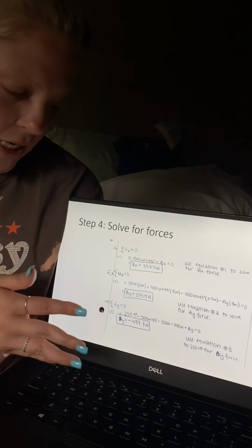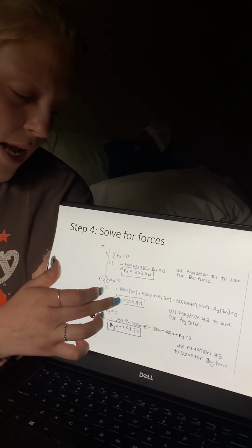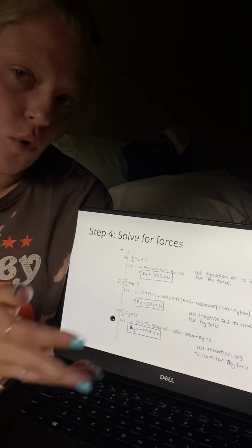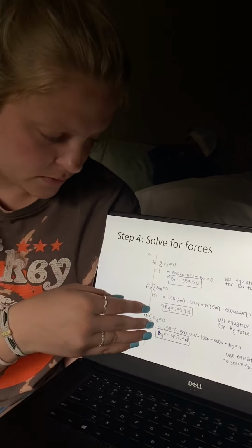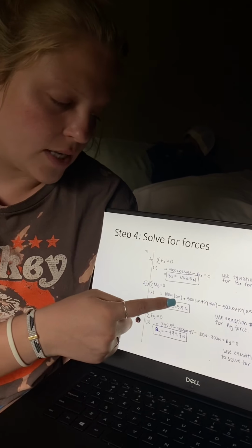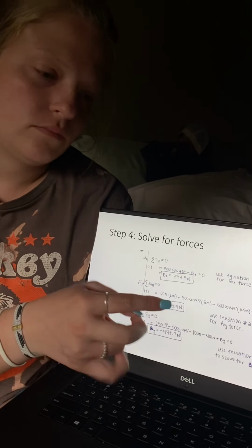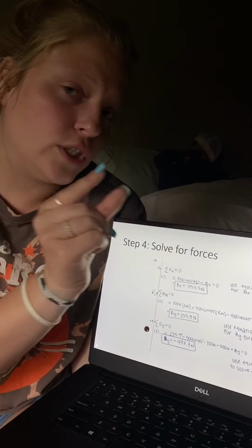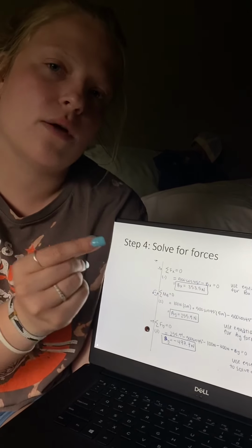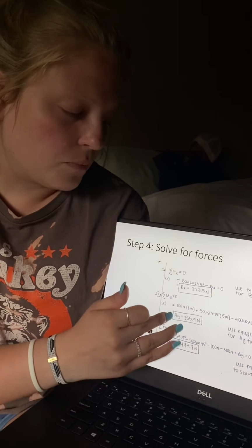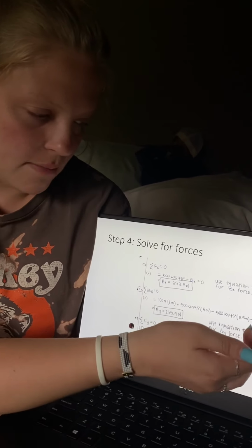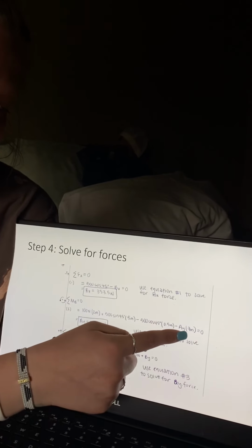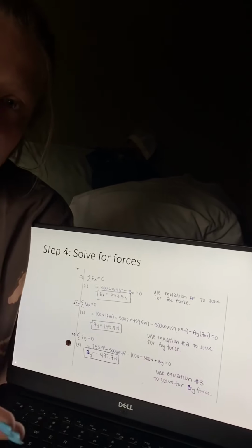So this one's a little trickier because we are multiplying the force times the distance of each component of the whole entire shelf. So 100 newtons times 2 meters is that first downwards force. From the B direction, it's only 2 meters, but if you were going from A, it would be 5. So on, we kept doing that the whole way, and the only unknown in this equation is AY times 7 meters. And that's 7 meters because